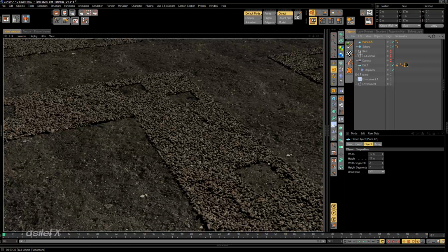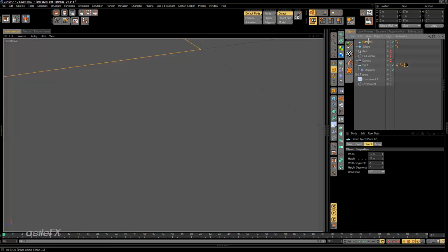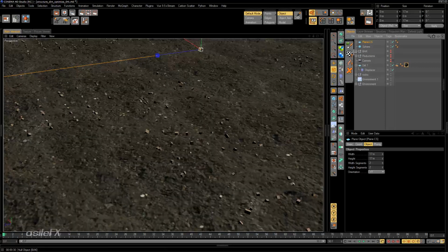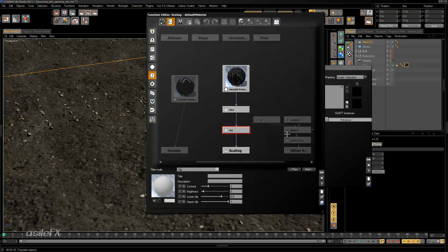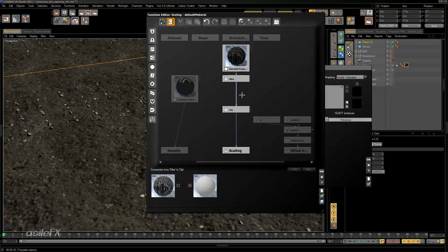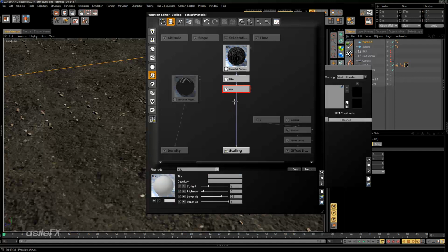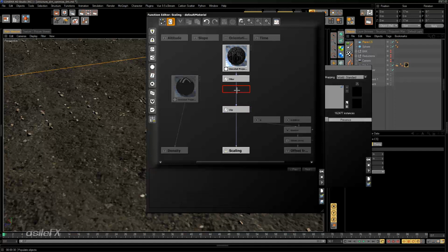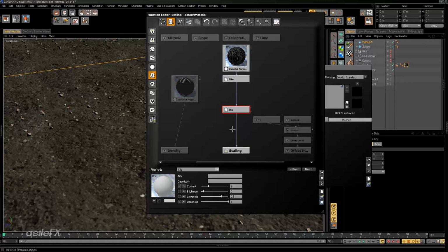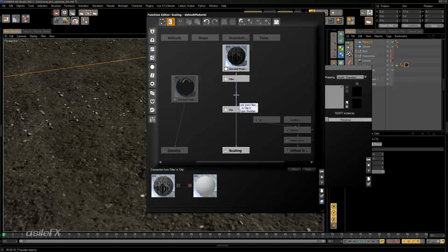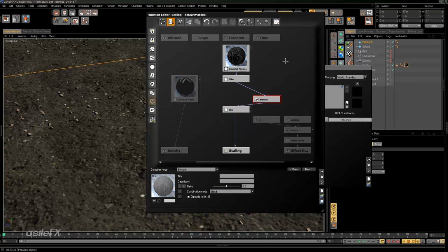If you do want to add a little more variability to it, since right now the scale change is really only effective within the slope range, what we can do is mix this together with a noise, just using a blender. We could do it before it's clipped in order to control our output a little easier.